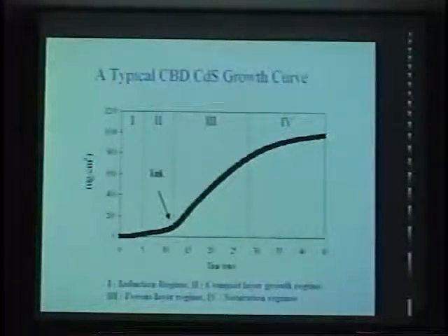Then the particles stick to the surface, so that's why you have a much higher growth rate. And since it's a batch process, once the reactant depletes, the growth stops, right? So then you can see this start to slow down and stop. Okay, so this is typically what you see in a batch CVD process.